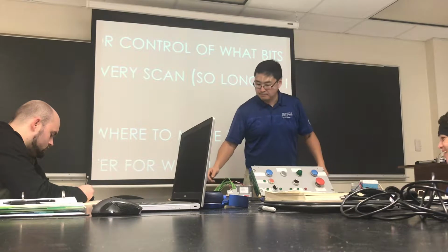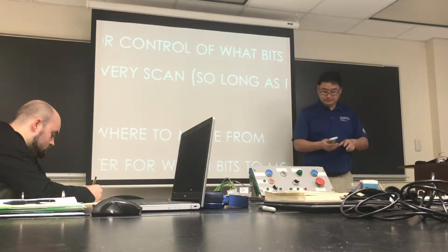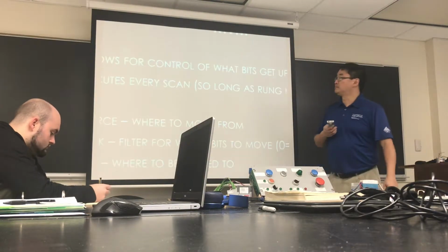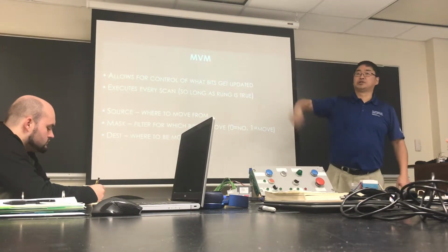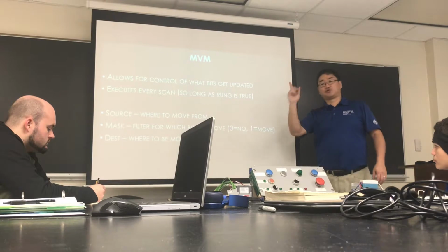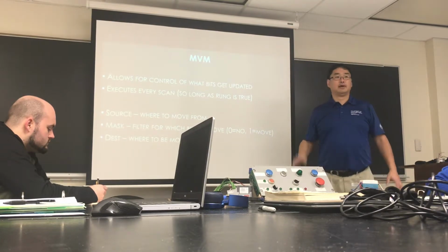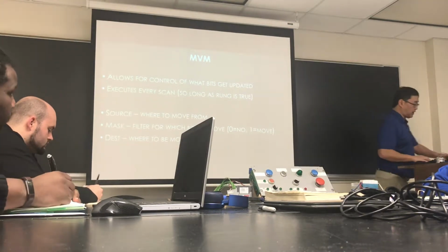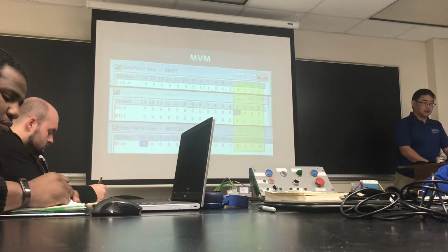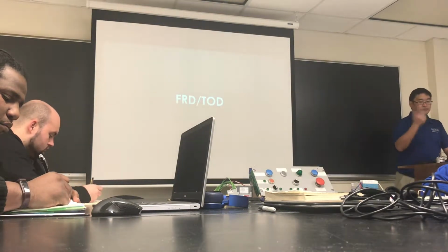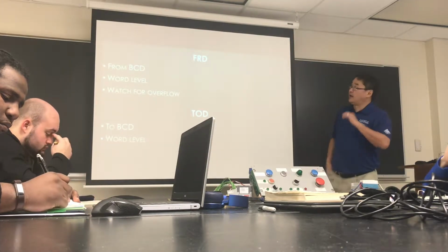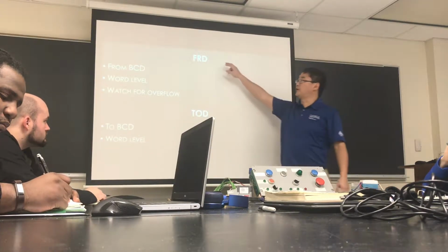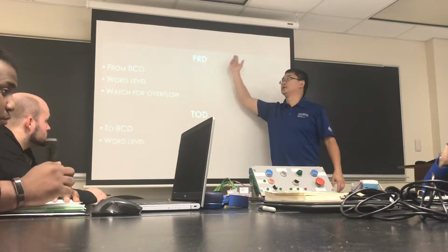There is a gotcha, and that is every time that rung scans, if it's true, it's doing the move. And that can really cause you problems down the road. Well, we'll get to that in a minute. Apparently we're going to do the BCD first. And so the 2 instructions for BCD are from and to, so Fred and Todd.